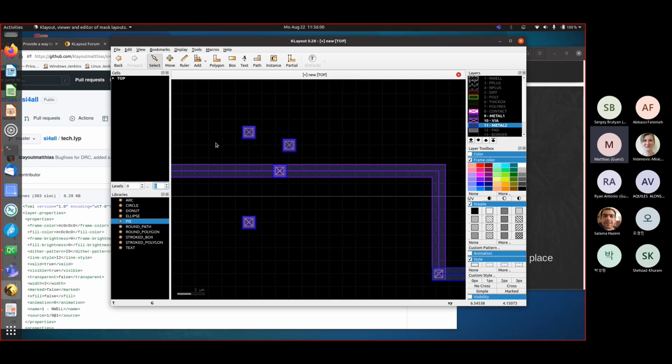Right? In Cadence, this is quite similar. I think you can just press 0, 1, 2, 3 to enable certain hierarchy levels, or Shift F. In my Cadence version, I'm using Shift F to display the full level of hierarchy. In KLayout, by default it's Shift star. So there's also minus and plus. You can switch the levels, and if you hit star, so Shift and plus in my case on the German keyboard, then you will show all hierarchy levels, which means you will show the content of all cells down to the very bottom ones.